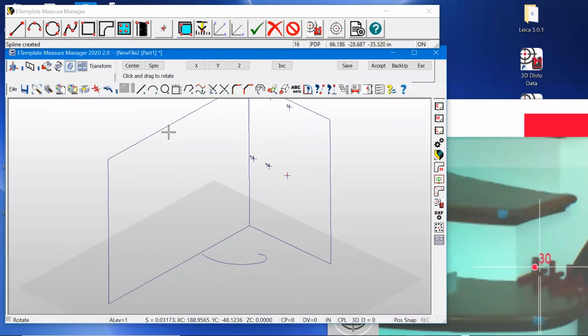And now what I want to do is I want to extrude that after I turn it into lines and arcs. So if we grab that spline, and I'm just going to highlight it here, now I can actually convert it into lines and arcs. And we know why we want to do that, right? Because CNC doesn't cut a spline.